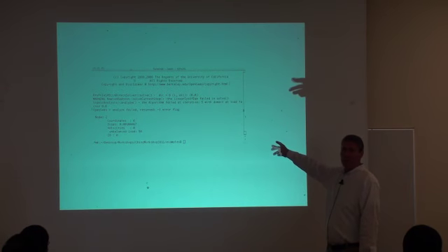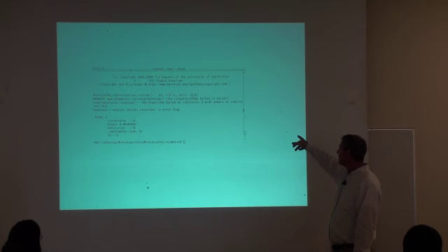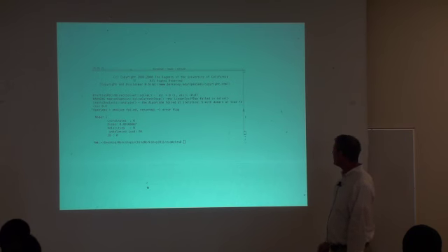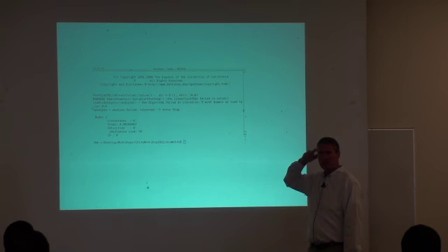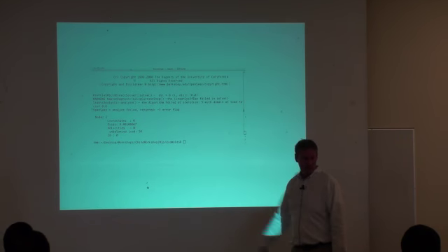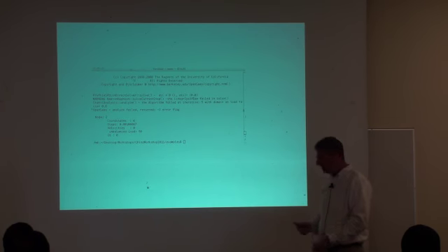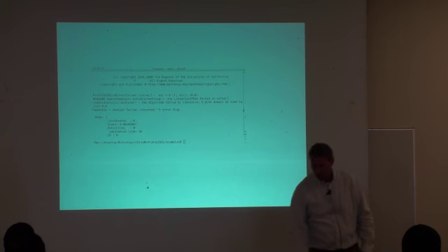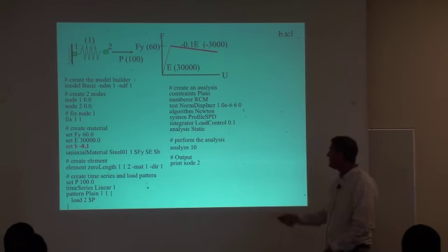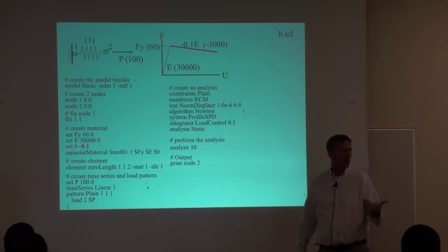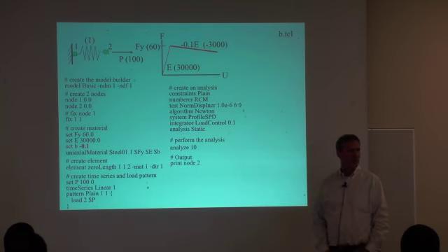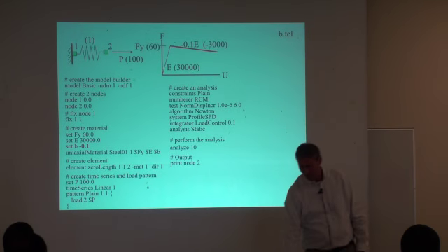And you see it doesn't fail at the start, it fails at an iteration where the domain's load factor is 0.6. So it fails when the unbalanced load is 50. See the results coming out from node 2? See this unbalanced load, it's saying it failed at 50. Now if we look at the model, 60 was where we should have got to before it failed. Why are we failing at 60? Anybody, any answers?